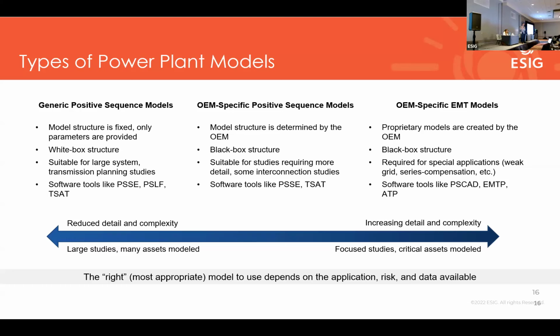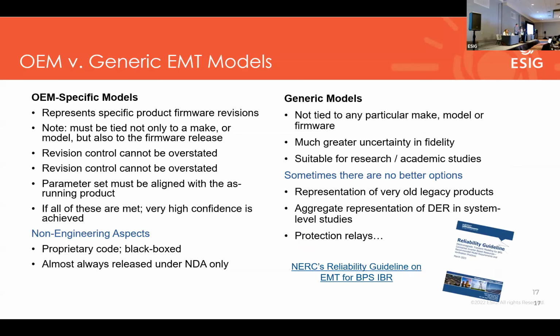That parallels what's been done with the OEM specific EMT models. They're proprietary, created by the OEM. It's black box from the manufacturers, basically exclusively. And they again have that increasing level of detail and complexity, and there are some extra hoops that go along with that. So now when we get into EMT models, there are generic models that are being generated, as well as OEM specific models, kind of like what was done for the positive sequence tools.